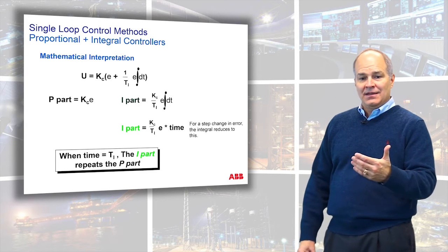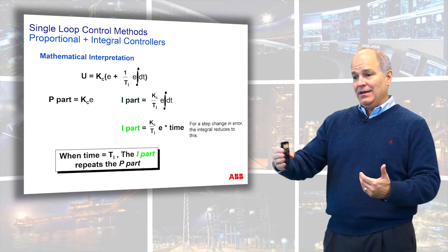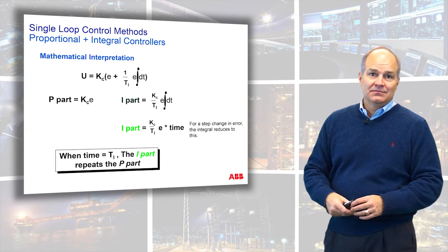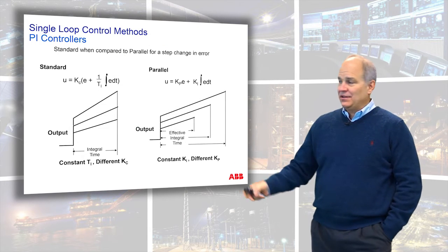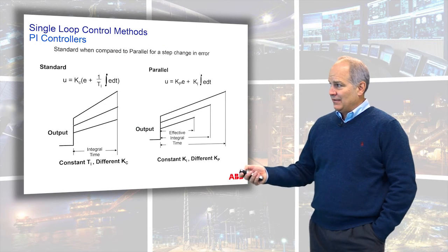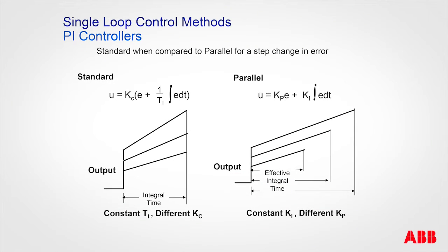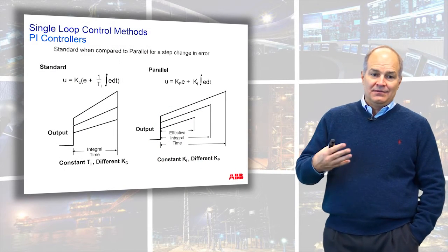Reset time, it's mathematically just when the two parts are equal. Okay? Now, I showed you this example earlier. Notice I now have the line drawn. Remember, I was showing this is the proportional kick. How long does it take for that proportional kick to repeat? Well, what if the proportional kick is this big? Notice they all take the same time. Okay, that's what's nice. That's why they call it standard or non-interacting.